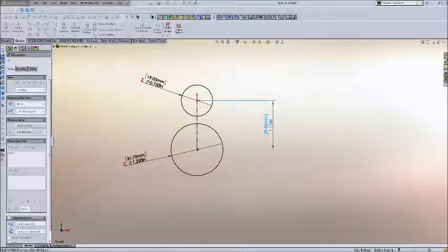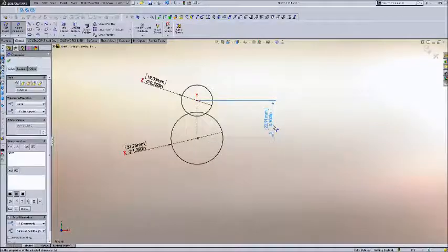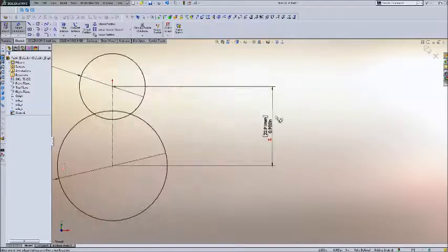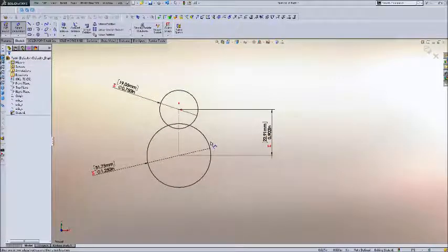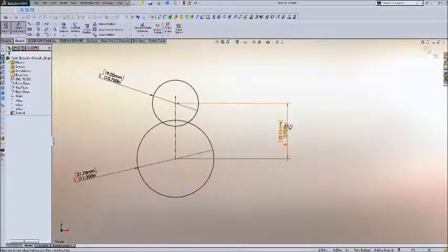What I do is I take a step further, and I'll add 2 thousandths. So I'll do plus 0.002. And again, you can't see what I'm doing, so I'll put it in the description of the video. When I do that, we're going to have our center distance being 0.902. Now without that 0.002, it would be a pretty clean number, 0.9. What that's going to show us is the extra 2 thousandths in there, so that 0.2 at the end.